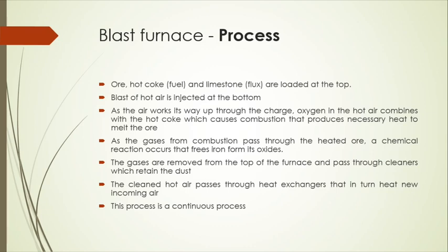As the gases from the combustion pass through the heated ore, a chemical reaction occurs that frees the iron from its oxides. Then the gases are removed from the top of the furnace and pass through cleaners which retain the dust. The clean hot air passes through heat exchangers that in turn heat new incoming air. So it's a continuous process: the heated hot air heats the fuel, the fuel causes combustion,